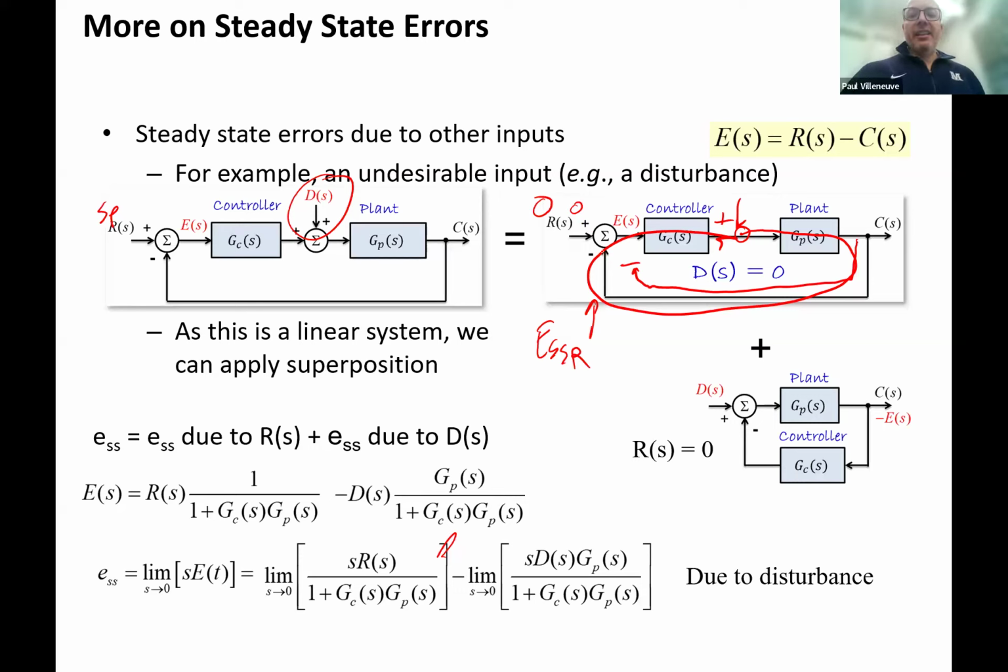I can replace that by just making this coming back over here into my controller. I can multiply that by a -1, because this is a negative number. It's always going to be 0 minus something. So my block back into the 0, I can throw that away because it's never changing. But what isn't changing is the fact that I've taken the negative of that number. So it's just the same thing as multiplying it by -1. So this is negative E of S, not positive, negative E of S.